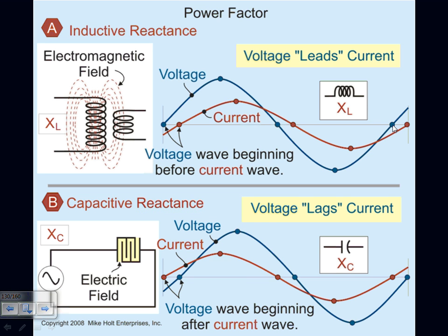Now, what happens if you keep adding more? You're getting into the leading power factor, and we talked about the problem with leading power factor. Here's 100% power factor. If you add more capacitors past 100%, you're going this way. If you add fewer capacitors, you're going the other way. So ultimately, you want to be hovering around 90 to 96. Ideally, 100 is perfect, but you can't get 100. Can you guys see these signals, what I'm talking about?